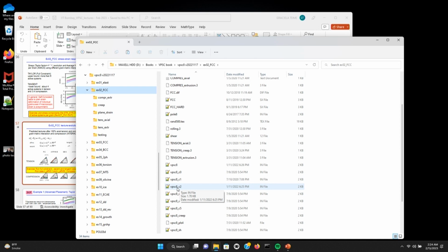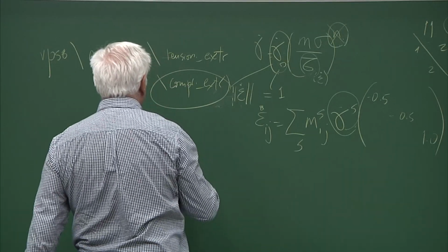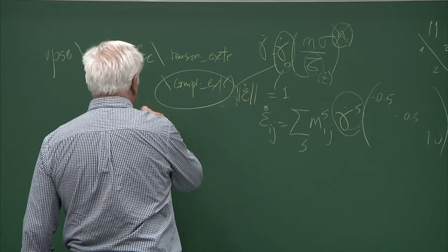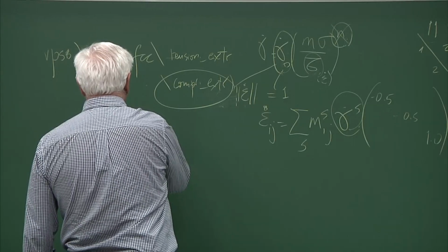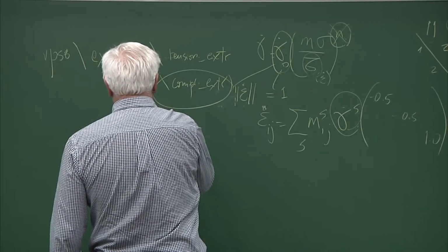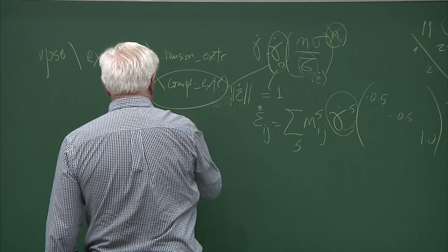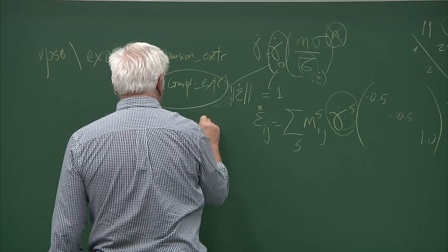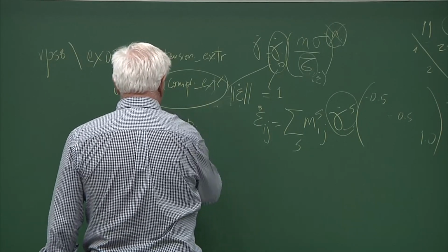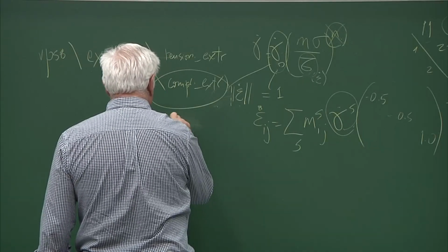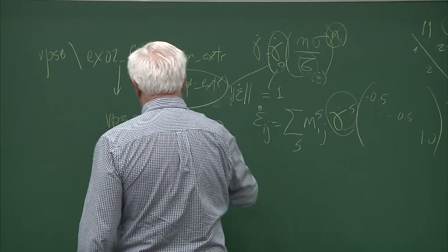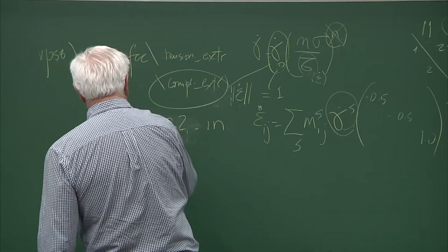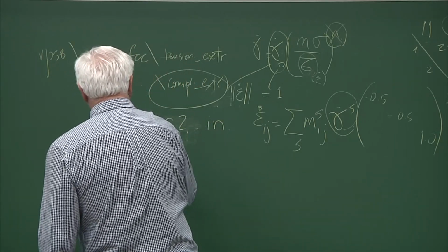We are doing compression, and we are going to be picking the file that is in this directory, which is VPSC8 compression2.in, and you will rename this file VPSC8.in.